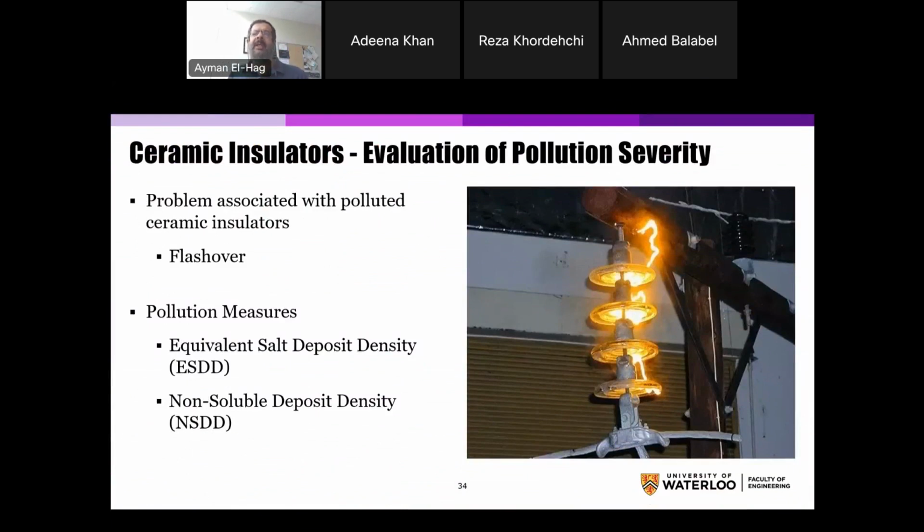has certain salt in it. If there's a humid day, like here we have some days that are humid. Fortunately, here in Canada we have rain, so rain washes the insulator, which is a good thing. But if it's just dew, then an electrolyte starts to dissolve, and then you will have surface discharge that can lead to a flashover.